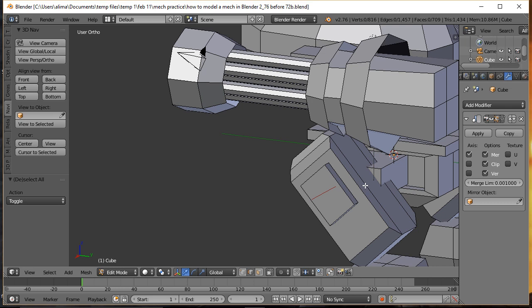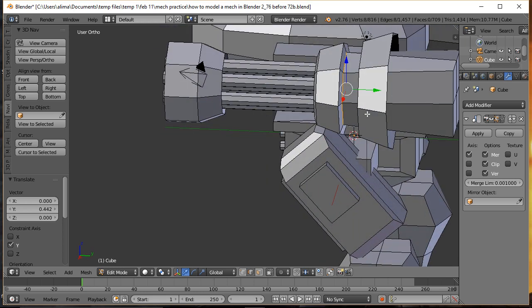Okay, and with edge select on, I'm going to hold Alt, select right here, pull this back some. I know it's probably hard to see in there, but I held Alt because I was able to see this edge here. When I selected, I grabbed the entire edge loop, and I just used the manipulator to pull that back, and hold the middle mouse button just to take a look now. Pull it back a little bit further. And I'm then going to press A to deselect.